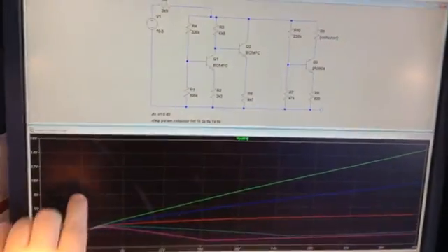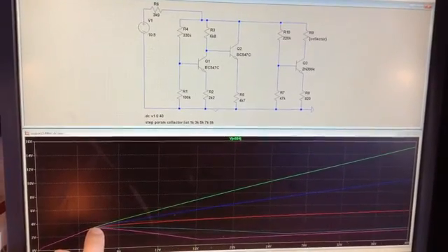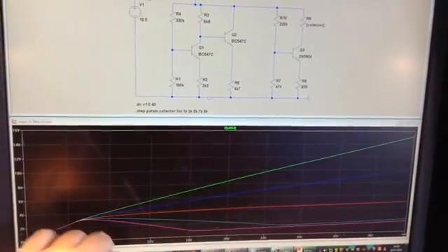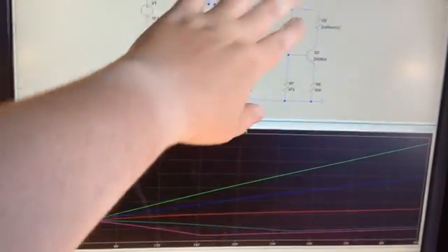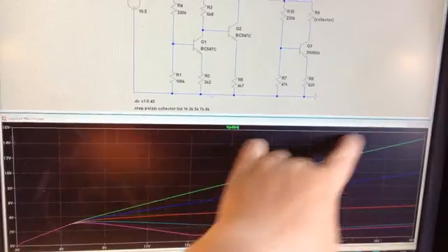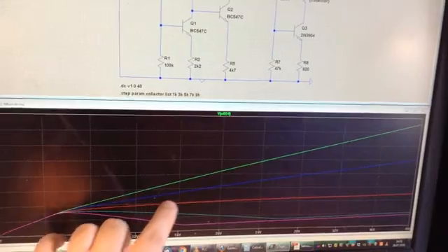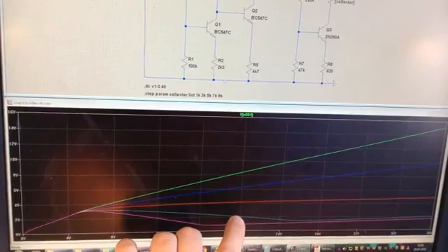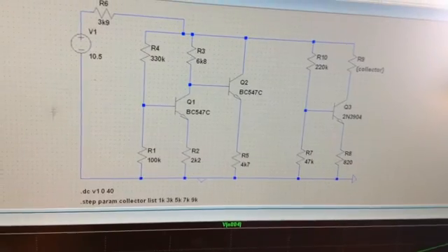And now you can see what happens. Okay, so you see the transistor turns on here, and the lowest value, 1K, won't have so much voltage drop over it, so therefore the voltage will rise. But 1K, 3K, 5K seem to be very close, and then you have 7K, which is too much, and so on. So I wanted to figure out how you calculate something like this.